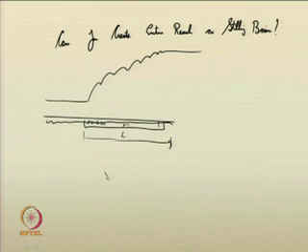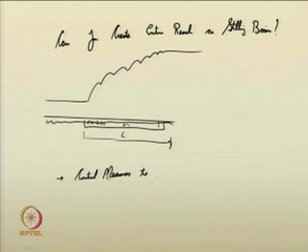Now, this will be non-economical if the length of the jump is too long. If it is a very long hydraulic jump, it will be quite difficult to provide the entire reach of that hydraulic jump as a stilling basin. So, you need certain control measures to provide the jump within the structure given.